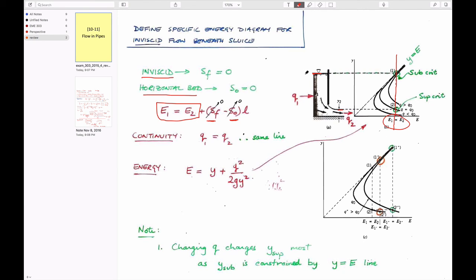And so if you have an upstream flow which is subcritical, which would intersect this curve for a particular flow rate, which might be this red one here, then if you know this height, you can calculate from the curve exactly what the magnitude of the energy is, because it's this value here, down to here.